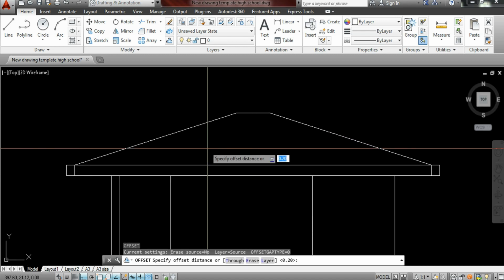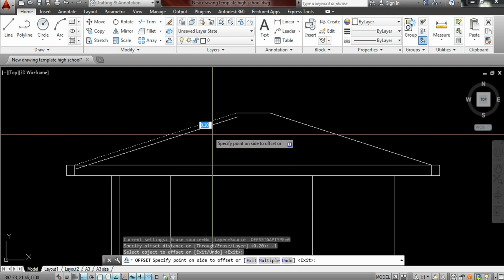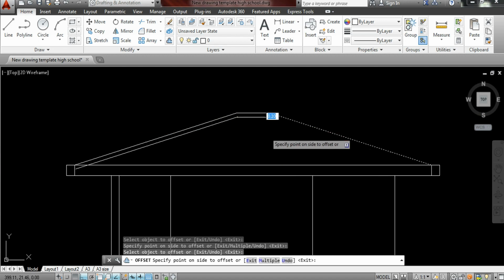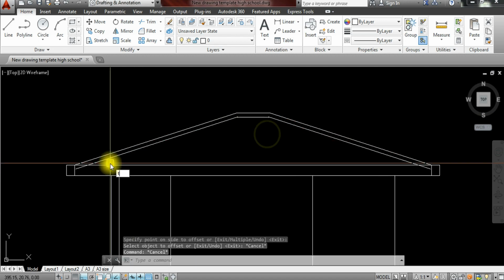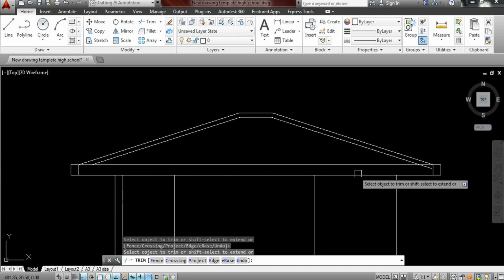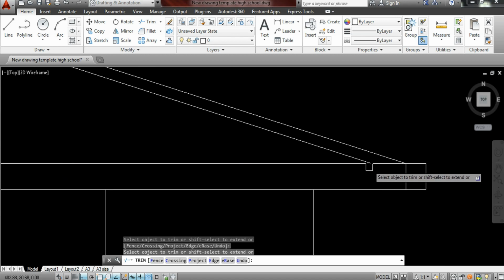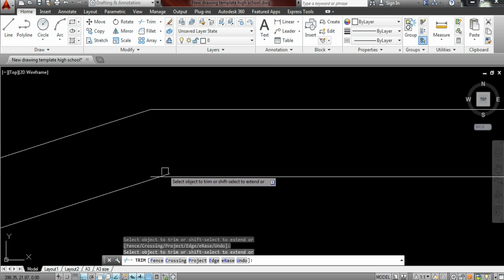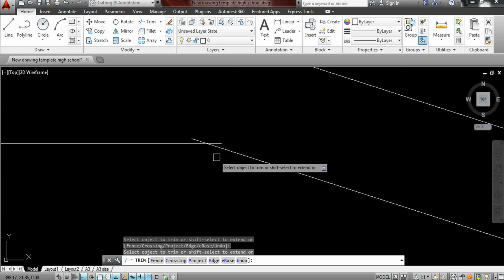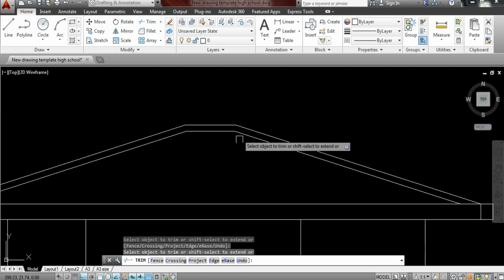Okay. So, offset. We used 0.1 before, but if you want 0.2 because your ridge is covered by a 0.4 distance, that's also possible. So I'll just use 0.2 here, which gives a 0.1 distance on both sides. So just click all the edges that are not needed.